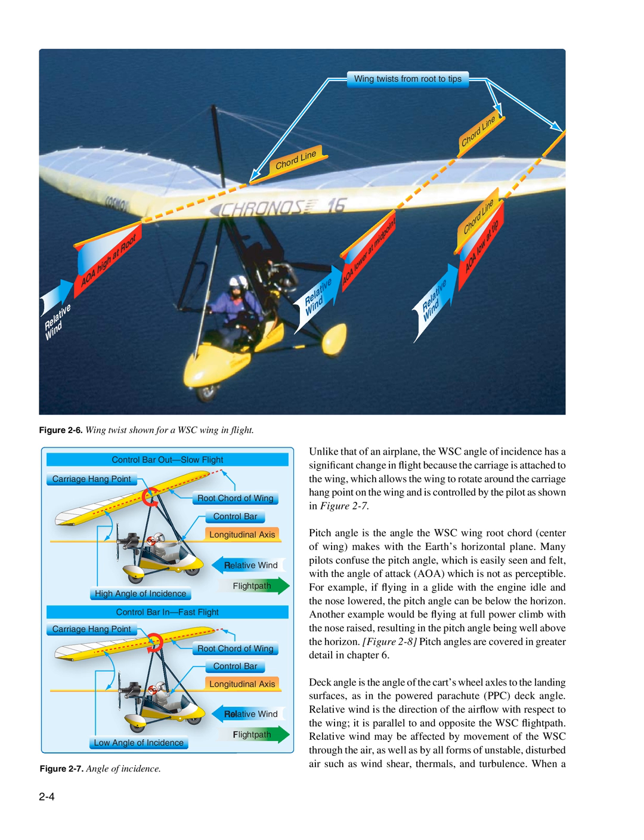Unlike that of an airplane, the WSC angle of incidence has a significant change in flight because the carriage is attached to the wing, which allows the wing to rotate around the carriage hang point on the wing and is controlled by the pilot, as shown in Figure 2.7.